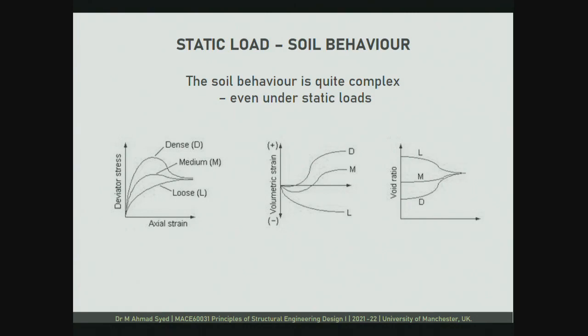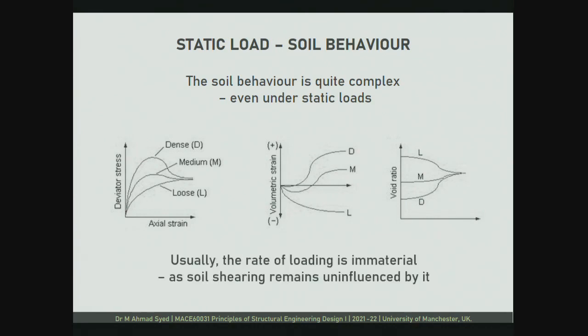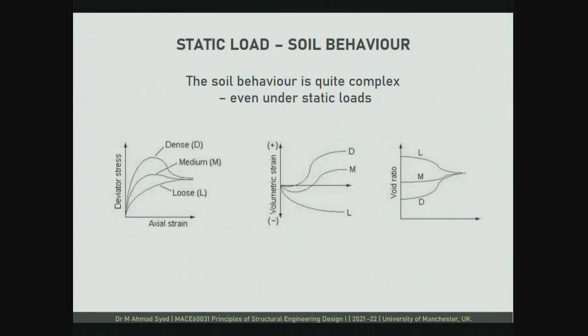If we are looking at granular material, then depending upon the state of the soil, your stress-strain behavior might be very different. For example, if you do a direct shear test on a dense soil, that soil might dilate. This is the dilatancy behavior of a dense soil, where with increasing shear stress and increasing axial strain, the soil, instead of getting compressed, starts to dilate; it expands. Sorry, an increase in volume. If you repeat the same test on a loose sample, then obviously the soil will compress, so there will be a reduction in volume. So volume will decrease, depending upon the relative density of the soil.